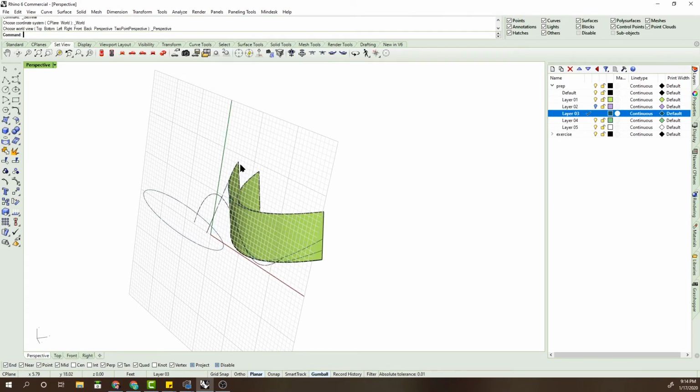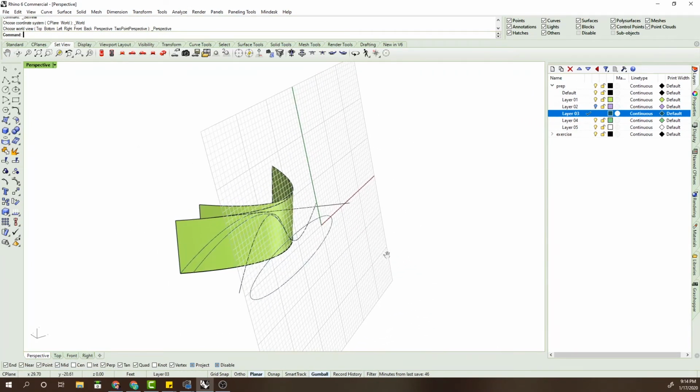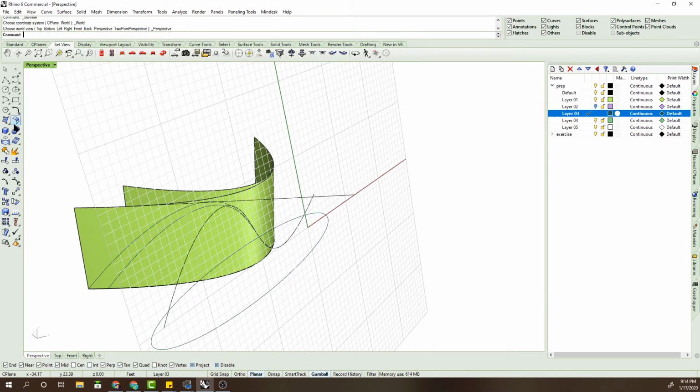Otherwise, the settings, feel free to explore the grid snap, which is kind of nice. You know, and there's things too. I was showing the rectangle earlier. You could do like the rectangle 3-point before you actually build the surface, and you could input the distance. So while I've started the command, as I'm about to go, I can hold shift and even tab to be perpendicular to that direction. I could type in a distance like 4 feet. You can see up here I'm typing 4 feet.